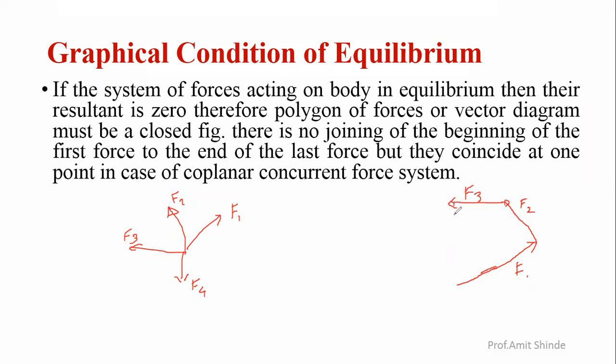Now if we are closing this fourth one, F4, what will happen? Where we started with force F1, F1, F2, F3 are the sides of your polygon, taken one after another along with their magnitudes and directions. In direction, if you see here, this incline makes the same inclination. F3 is horizontal, and F4 is vertical, with the same inclination over here, along with the magnitudes.